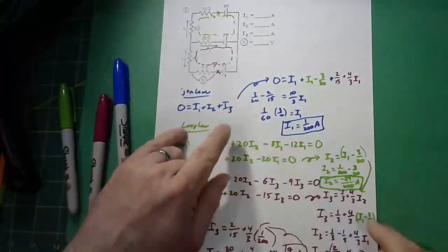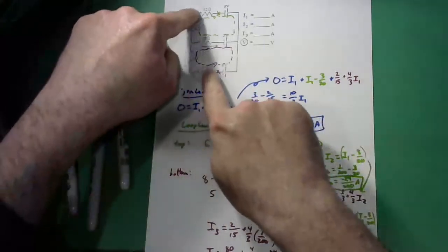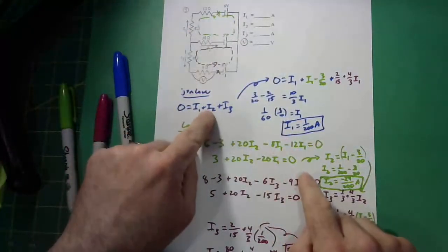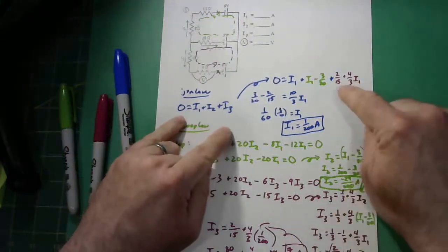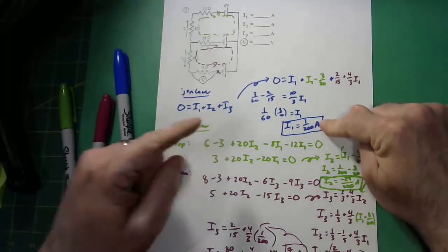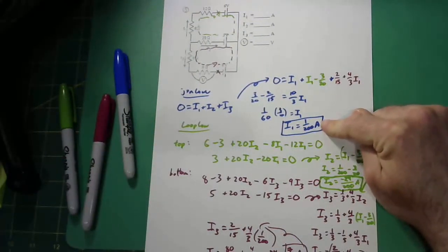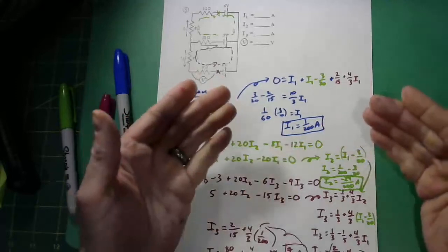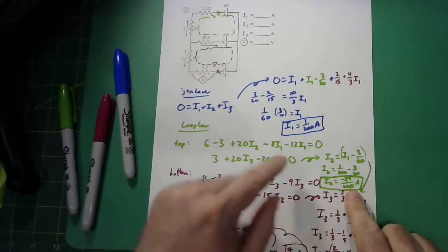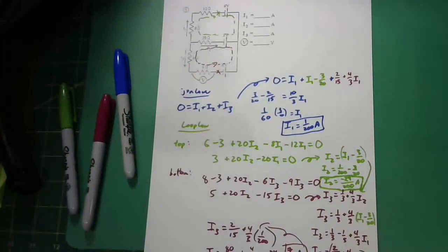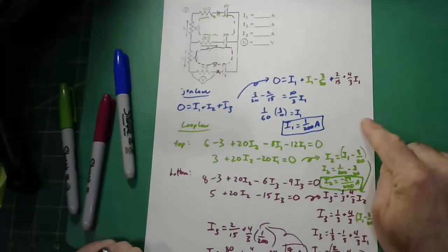This had better work, right? So you say, hey, I1 and I3 that are pushing in this way had better add up to balance out I2. I1 is 1/200th. I3, you know what 7/50ths is in 200ths? That would be 28/200ths, right? Times 4 times 4. 28/200ths plus 1/200th is 29/200ths. Oh, look, minus 29/200ths. That balances out to 0. Perfect. And that is circuit problem 5.